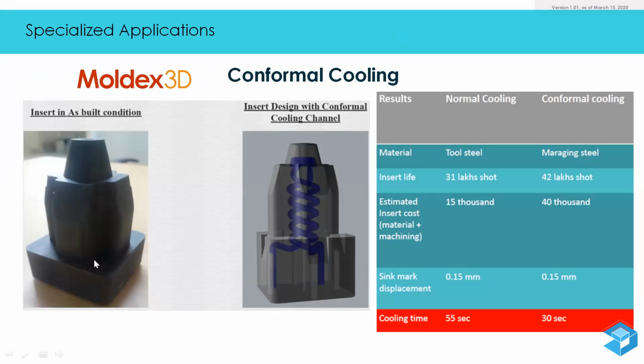But no, there are actually helical channels present inside. You move the part, and you can see there are two holes inside, through which you can flow in the coolant to cool the component. Such difficult to make designs are possible using additive manufacturing processes, and that is how the industry is advancing right now.